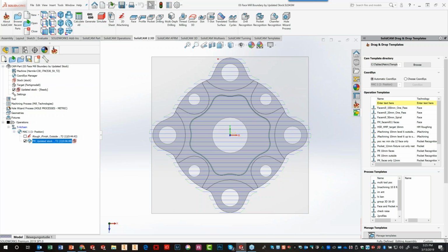And what you can see is that your toolpath has completely changed, because now it's according to the boundaries of the way the stock is right now. So you don't have to touch the geometries. You'll also note that there is no geometry for that as well.